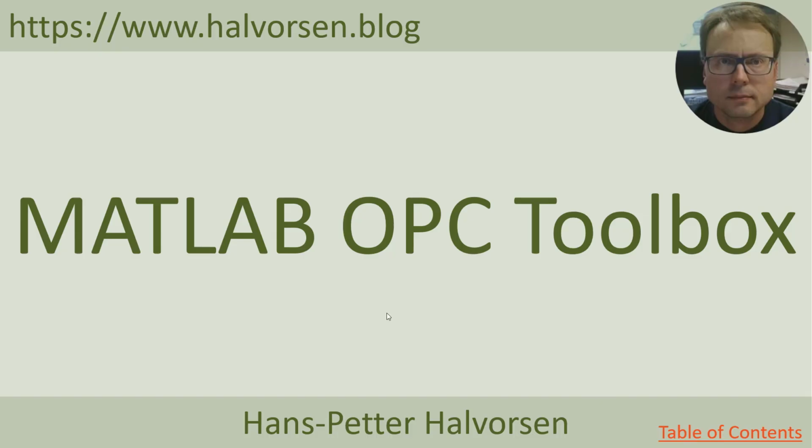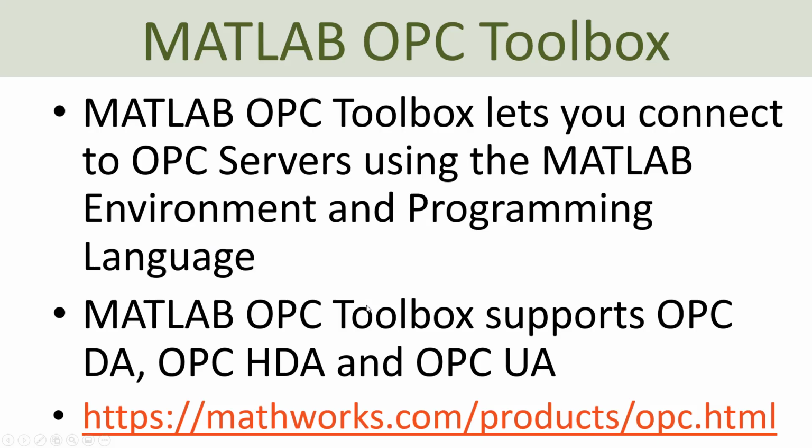So now next let's start using Matlab and the Matlab OPC toolbox. So with the Matlab OPC toolbox you can connect to different OPC servers, both classic OPC servers but also OPC UA servers. And you use the traditional Matlab programming environment. So this Matlab OPC toolbox supports both OPC DA, OPC historical data access, and the new OPC UA standard. You find more information about the toolbox on the vendor's webpage.